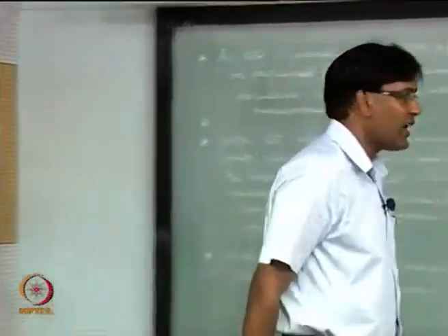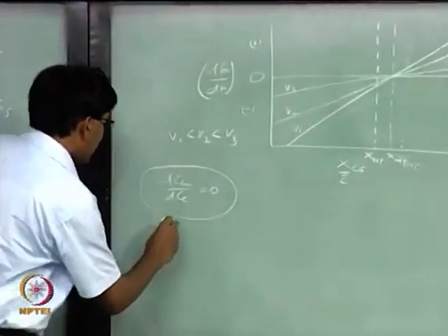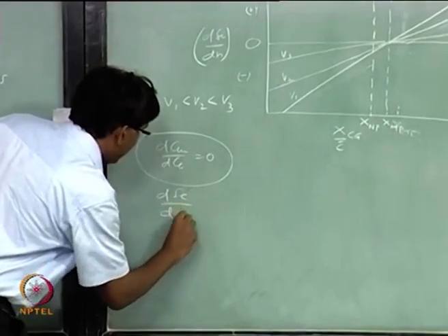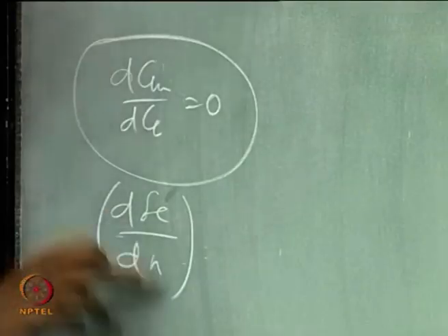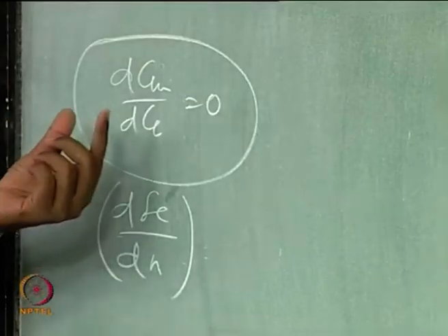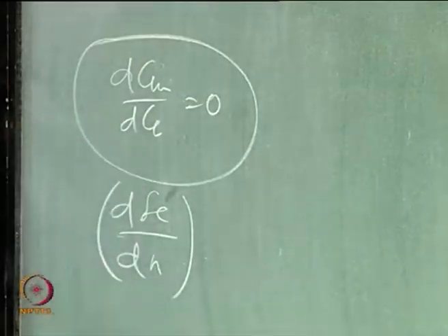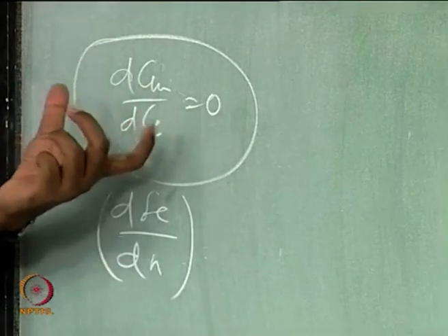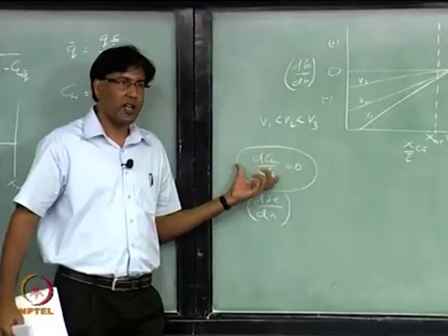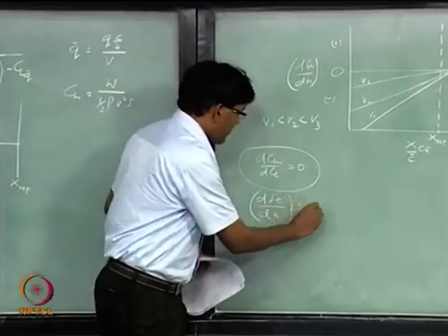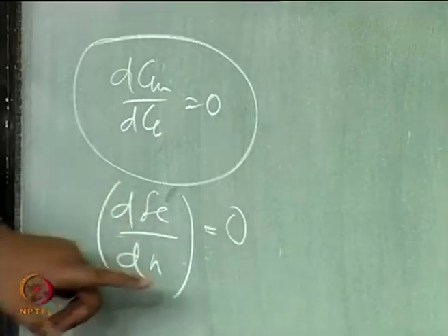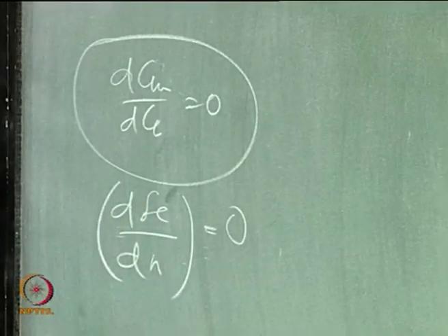Okay. So, try to see what is the relation between this and this. So, this dCm over dCL with pitch rate effect included, right. When you solve this for the CG location where this becomes 0, it is equivalent to finding the CG location through this relation, okay.